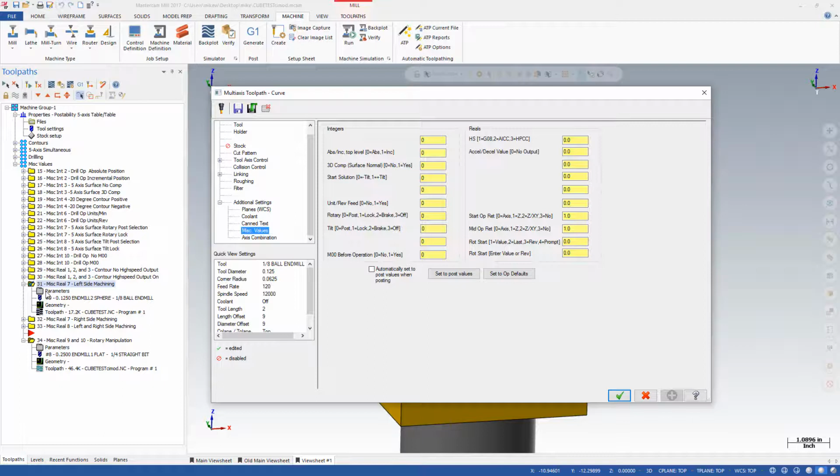1 will set the retract along a single axis, which for most machines will be Z, but some may use X. 2 will retract the same as 1, but will also add homing of the other two axes after. 3 will cancel any retract, even those the post has created, and use the clearance height.